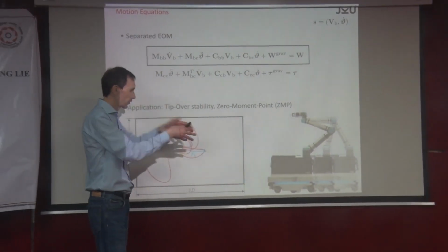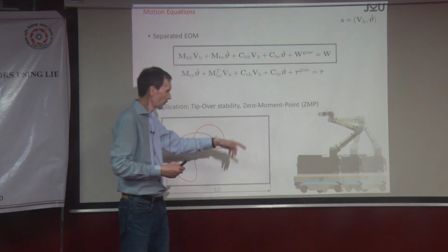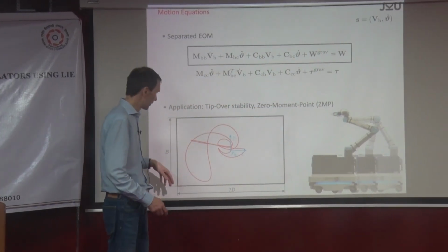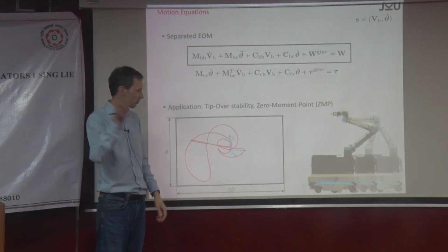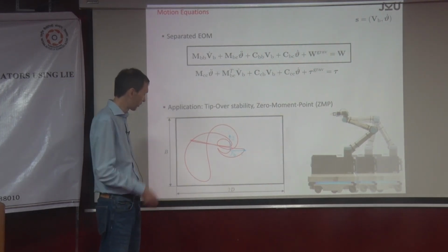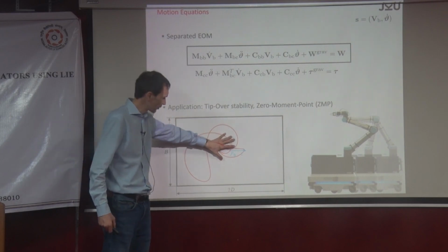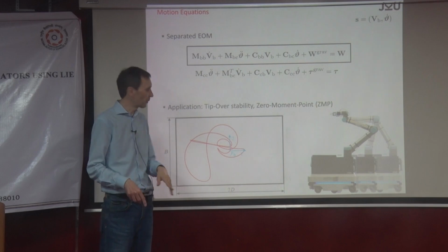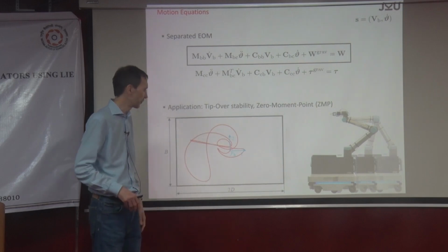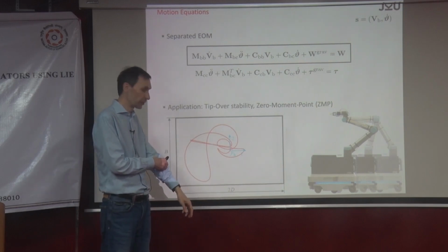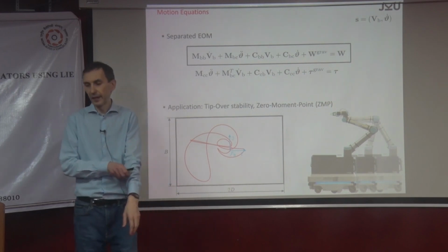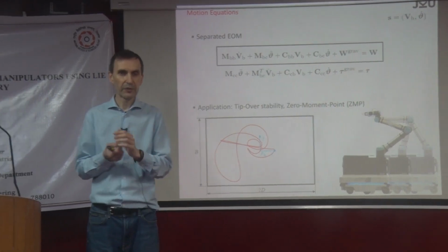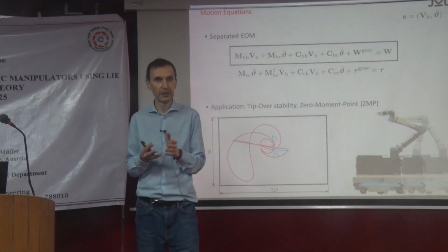This is what we did for this system. This was an Austrian research project. I don't know what the motion was. It was a high-speed motion, and then you get whatever you get. The good thing is, this is the trajectory of the zero moment point, and apparently it's all the time within the support polygon. And this of course includes the full dynamics, right? What you said with the center of mass is more like a static consideration.